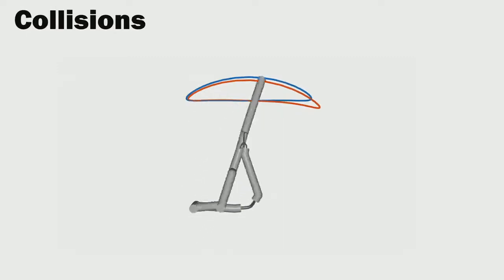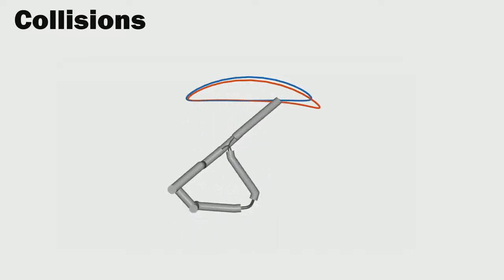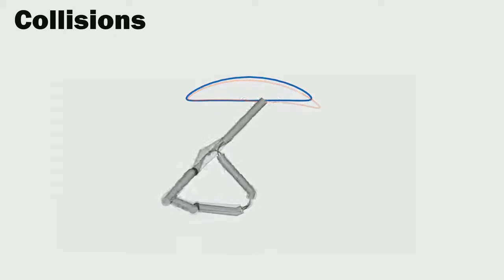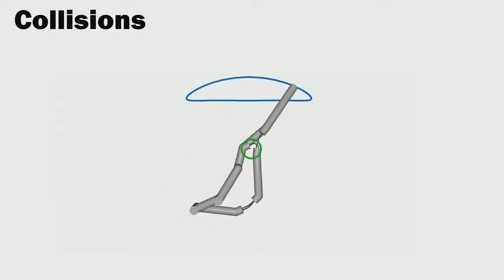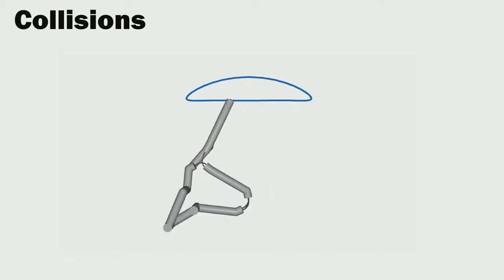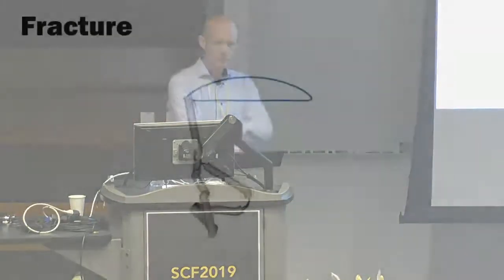One problem that we have, however, in this case, is that while the optimization moves flexures around, we might run into intersections between the components. And quite obviously, when we would print that mechanism with intersections, that wouldn't really work out so well in practice. So we're making an additional design objective that asks for no intersections at all, a strong penalization. And when we're using these two objectives together, then we get this performance here, which is still matching the trajectory quite well, but without any collisions.